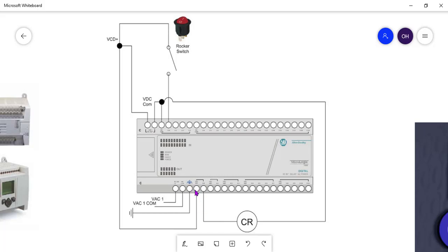So here you have power coming in, but it cannot go to this relay to complete the circuit. Get this negative until the program inside is executed. Only then can the program allow this link to be established. So a program is required, called ladder logic, or statement list, or function block. But for the sake of our level of training, everything I'm going to do for now will be restricted to ladder logic, which I will discuss, then function block and statement list when it is time.